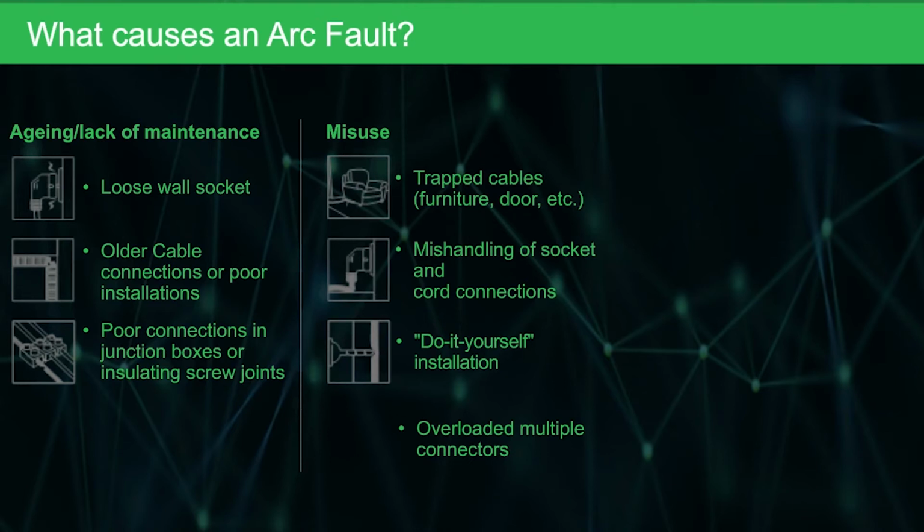The other one is misuse. A more common situation within our homes and the office environment is power supplies for our laptops where the cable's been pulled too many times and is sticking out the back of the transformer, or office chairs rolling over extension leads sitting on the floor. So that type of misuse, we obviously have test and tagging in place within the industry.